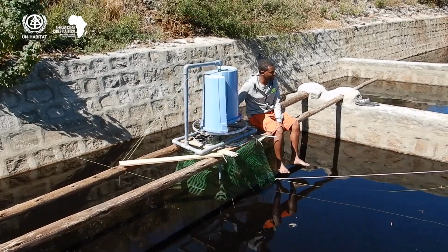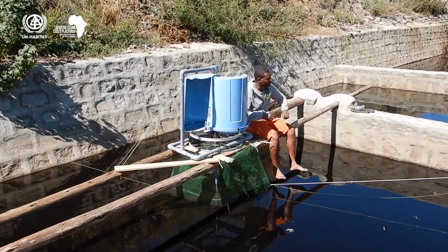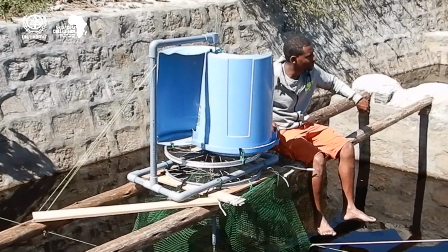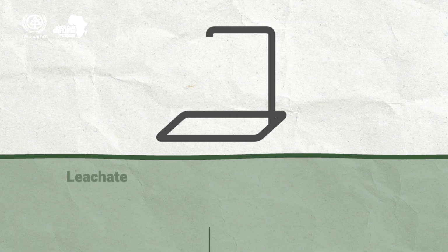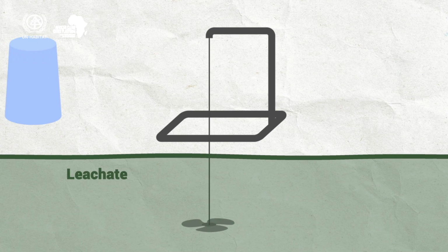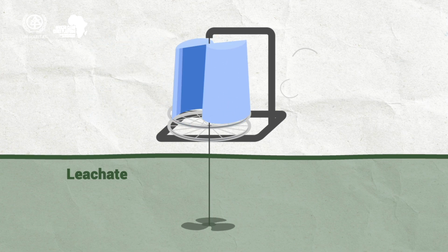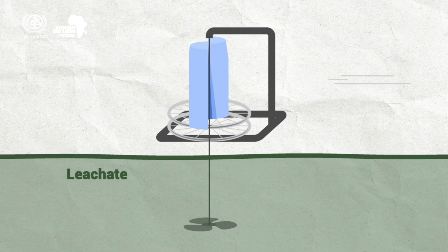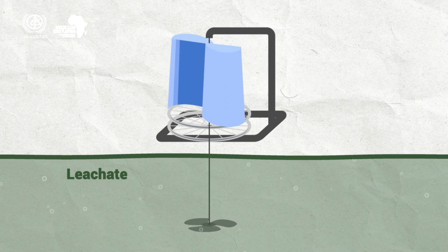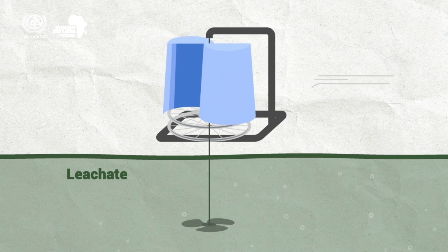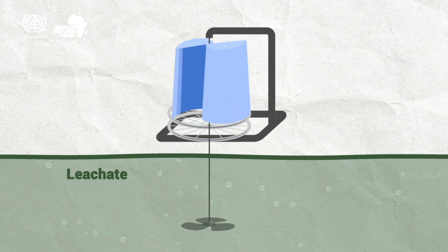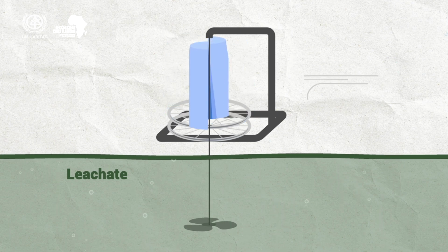One simple way is the installation of an eco-fan, which you can see here. It's made from a dustbin, bicycle rims, and the plastic blades you'll find on general household electric fans. The fans, placed under the surface of the leachate, rotate by winds collected by half-cut dustbins, stirring the leachate. This enhances the aeration of leachate. An eco-fan is a good, low-cost, low-maintenance starting point for leachate treatment.